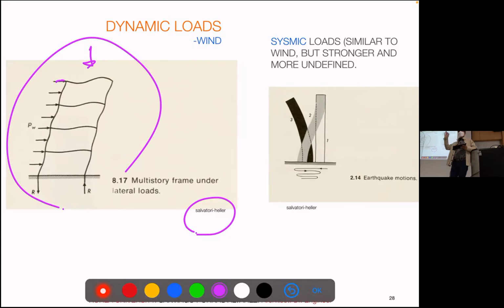And apart from conventions, I'm used to putting a positive moment where the bending happens, right? This is an inflection point, and then another one. So this is the moment for that element, right? And this moment will be like this. Always putting the positive moment on the bent area is very graphic, very easy to see. And the deformation will be a parabola, probably a second or third degree parabola, because of the integral of that line.